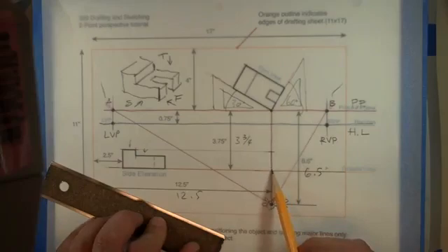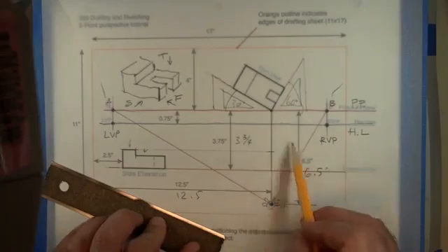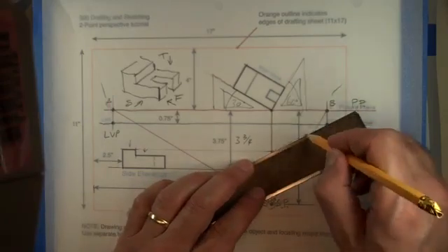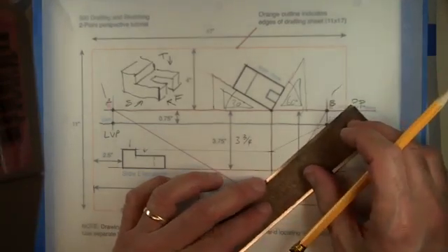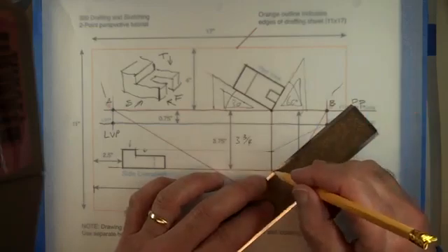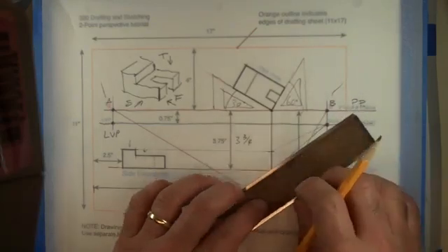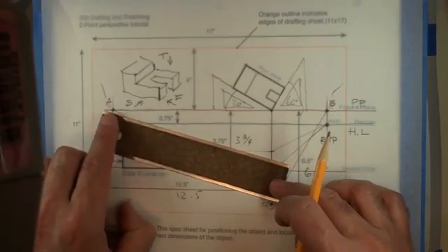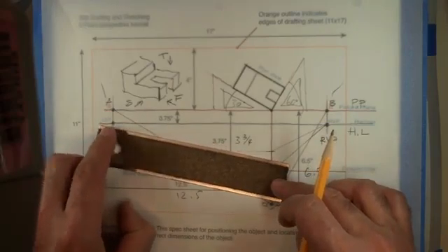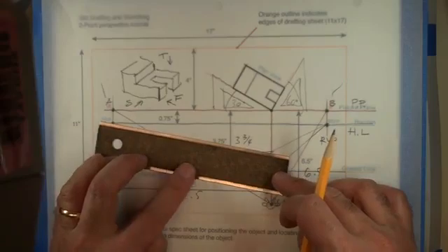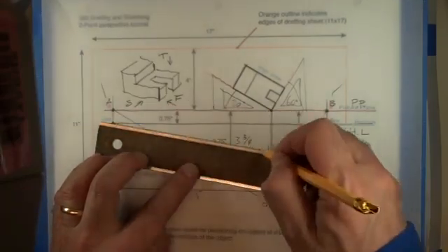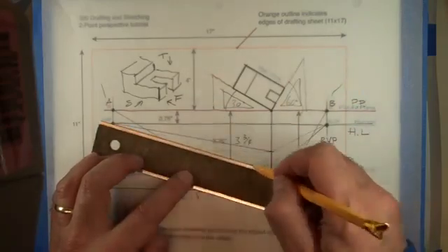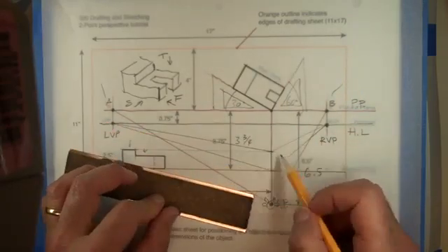Okay, once you have the leading edge here, let's connect now to the vanishing points. So we just simply draw lines from top and bottom endings. And again, try not to get confused and use A and B. You have to use the vanishing points right below it. Like that. So now we start seeing the sides.